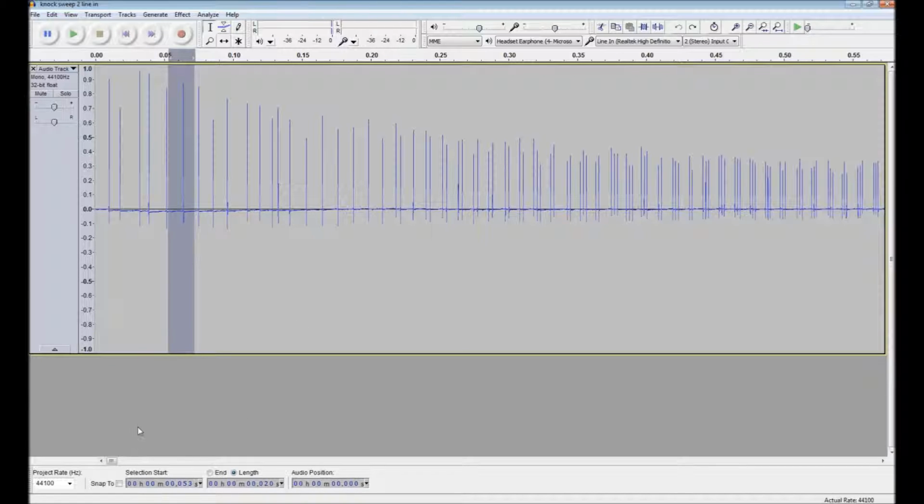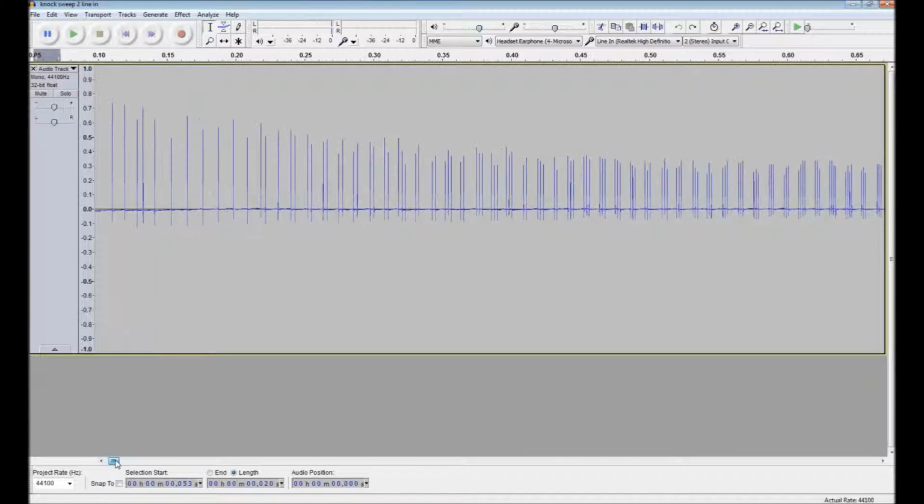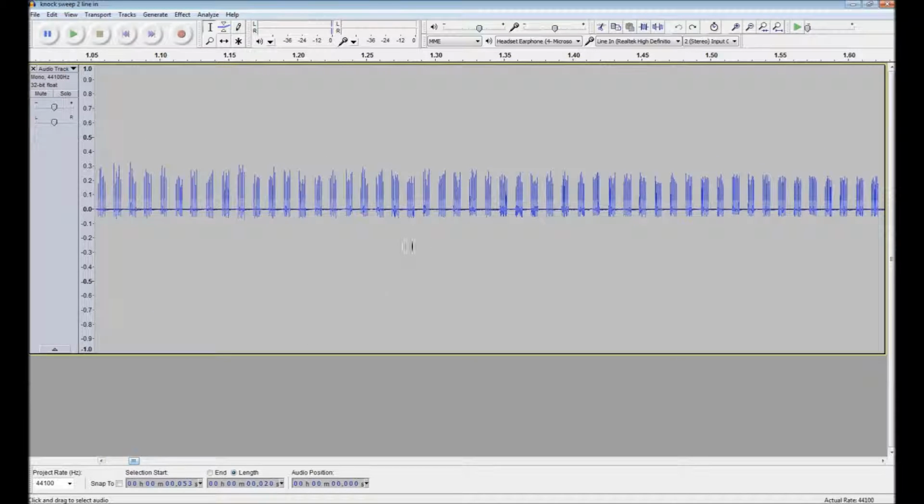This is called interference, and this is why we see the reflection back from 15K down to 7500 and below, and it still triggers a knock event even though we are past the main knock window. And you can see these lines.